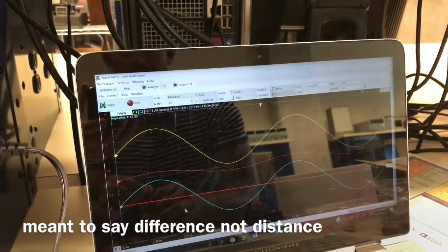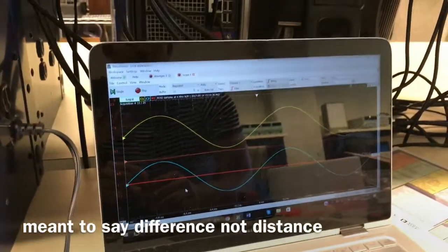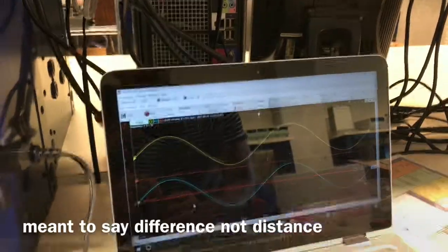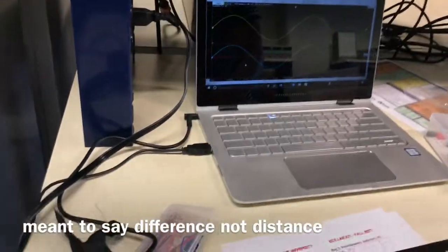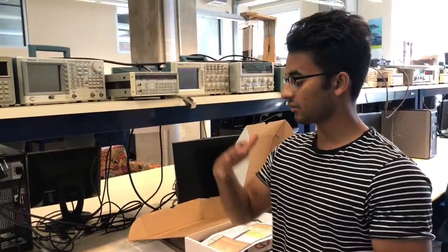And the goal of this lab was to find a resistance which would minimize the difference. So we found that to be about 4.7 kiloohms, which we measured after we disconnected the potentiometer. So the goal of this lab was to find the value of the resistor that would minimize the difference